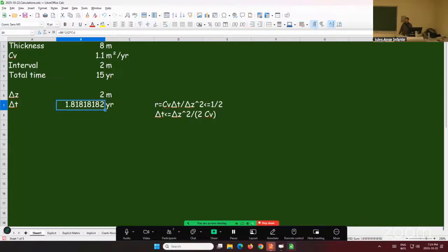Even if you're using finite element, it's not bad to think of it in terms of this explicit method. To give you an idea, your mesh may be too fine for the time step that you're thinking. There might be some errors implied within the calculations that you're not aware of.